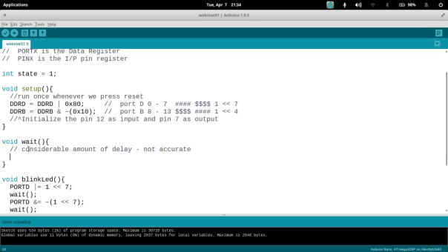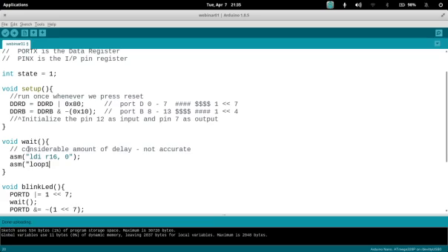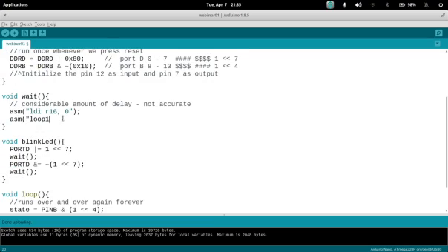The main thing I'm emphasizing here is that we can also use inline assembly. So let me load immediately into R16 a value of 0, and then I'm going to take a loop, let us say 1, just because we have already a definition for loop in here. I'm going to take a loop 1 label, and in this I'm going to decrement this R16 value.